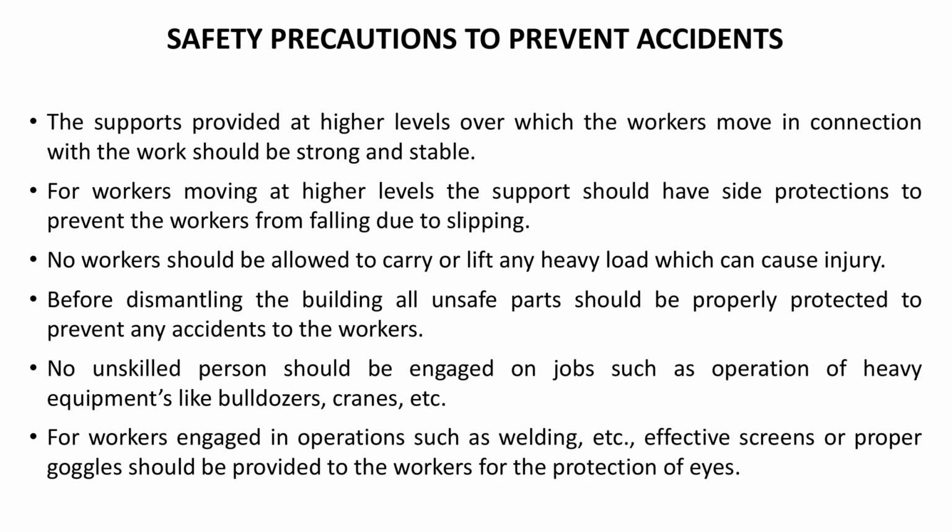No workers should be allowed to carry or lift any heavy load which can cause injury. Before dismantling the building, all unsafe parts should be properly protected to prevent any accidents to the workers.